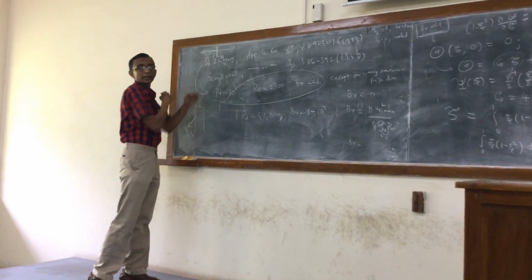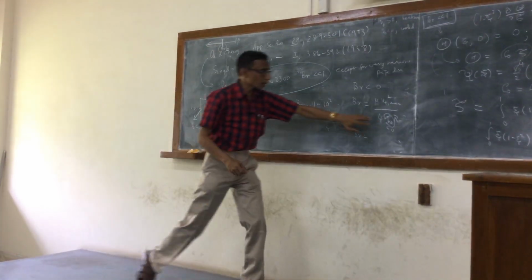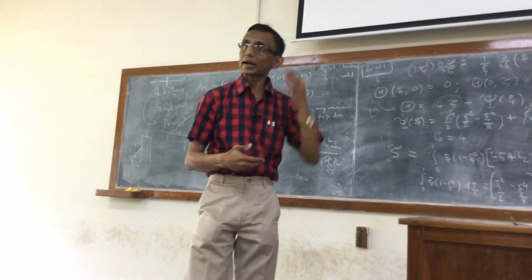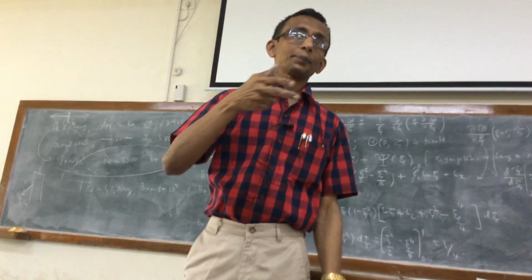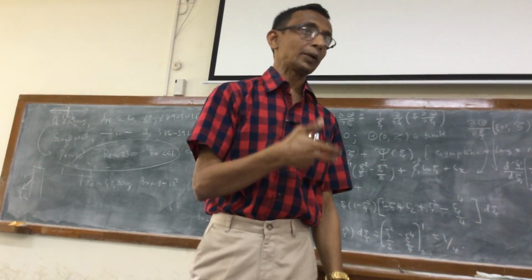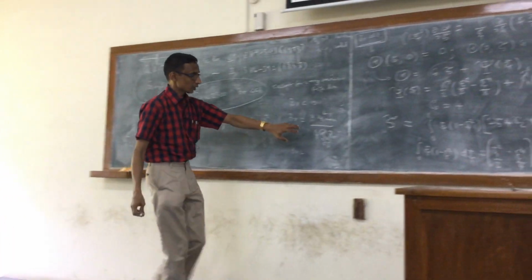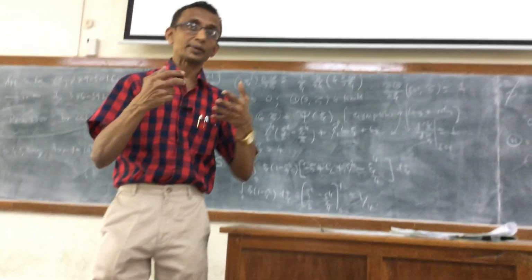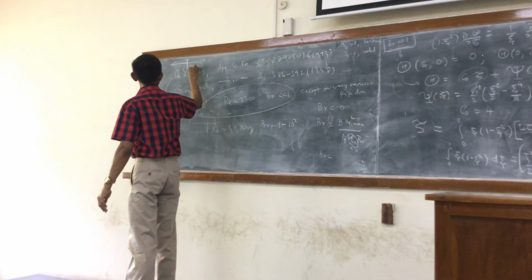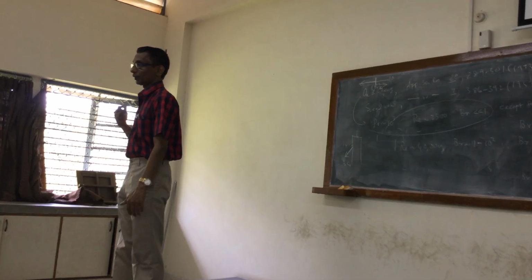So if you are in this range, beyond this, that means the magnitude of Q0 is not sufficient, so we are not removing as much heat as is required. So the viscous dissipation is dominating over Q0, and actually the fluid is getting heated, whereas the purpose is cooling the fluid. So you have to ensure enough removal of heat, that means the magnitude of Q0 should be sufficiently high so as to shift the Brinkman number to the right of the critical Brinkman number.